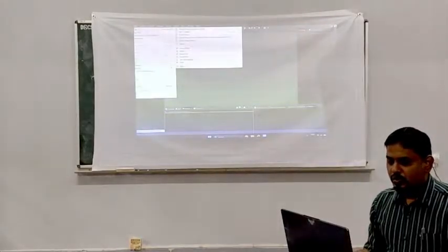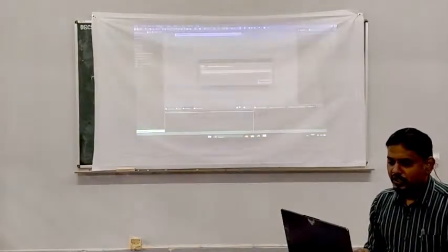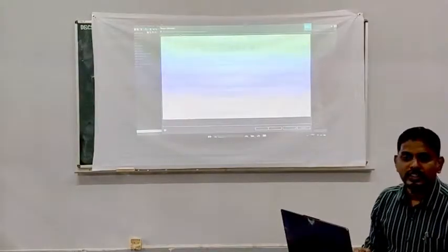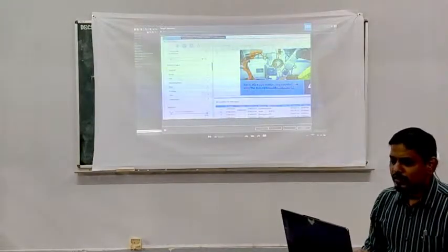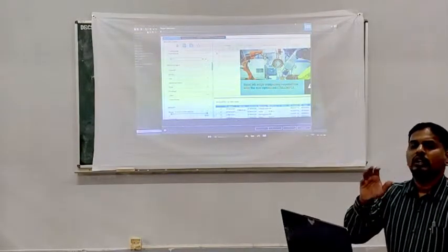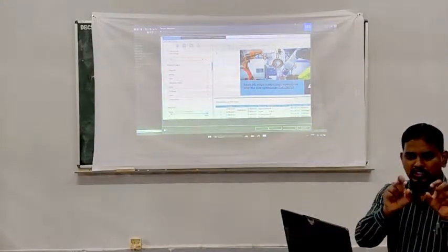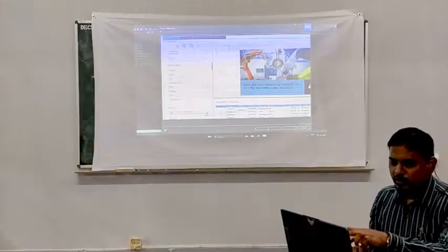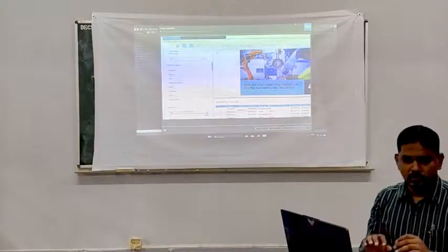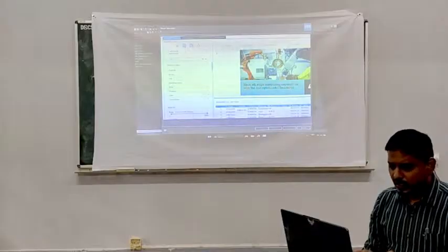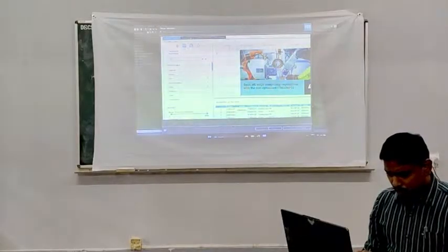Yeah, so now it's fine. Everything is updated for me. Now after that, STM32, one dashboard will open. It's a target selection board. There, suppose we use a separate microcontroller, if you have the chip with you, you have to go there and type your part number. But what we are going to use is a board. So you select the board.